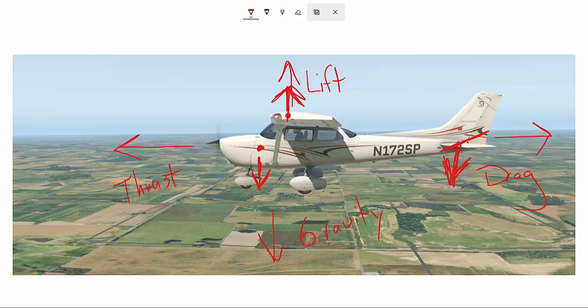And those two counteracting downward forces, both in front of and behind the center of lift, give that aircraft a lot of stability. It gives it the ability to return to the original position in which it was after you stop adding input through the control yoke. I hope that helps you understand a little bit about the stability of an aircraft.